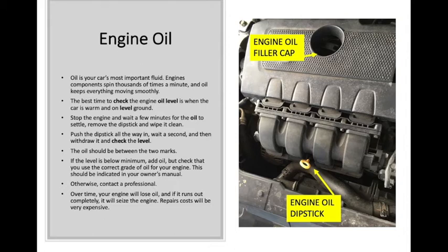Remove the dipstick and wipe it clean. Push the dipstick all the way in. Wait a second and then withdraw it and check the level. The oil should be between the two marks. If the level is below minimum, add oil, but check that you use the correct grade of oil for your engine. This should be indicated in your owner's manual.